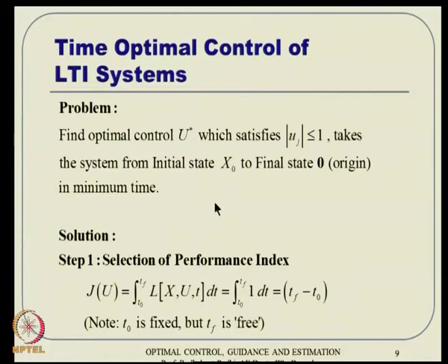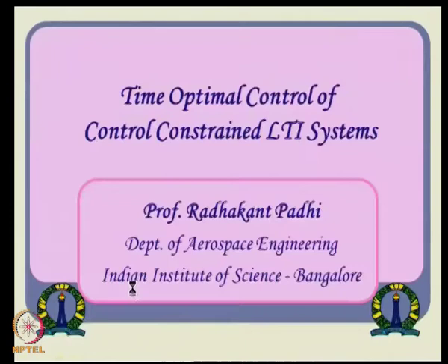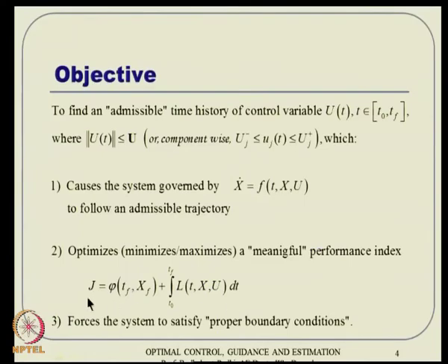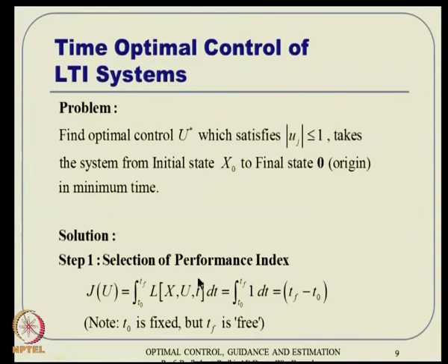First thing first, we want to put our objective in mathematical form. What we are interested in here is time optimization, in other words a minimum time problem. Going back to the control structure in the very first slide, this objective function needs to be defined. Here we can take phi equal to 0 and L equal to 1, and then we end up with this cost function, integral from T0 to Tf of 1, which is nothing but Tf minus T0.